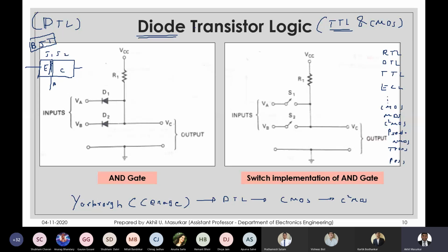If J1 is forward biased and J2 is reverse biased, the BJT is in forward active mode, and when J1 is reverse biased and J2 is forward biased, the BJT is in reverse active mode. So when the junctions are one reverse biased and the other forward biased, the BJT is in active mode. Which active? Forward active or reverse active?